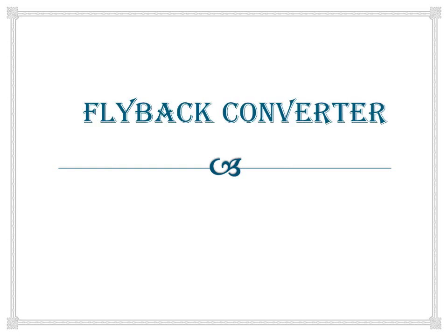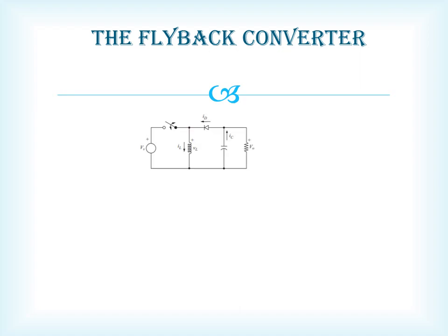The first topic of our discussion is flyback converters. Do you remember this circuit? This is the circuit of the buck boost converter, which we have already discussed. So what is the expression of output voltage in case of the buck boost converter? It is given by minus of Vs into D upon 1 minus D, where Vs is the supply voltage and D is the duty cycle of the switching waveform.